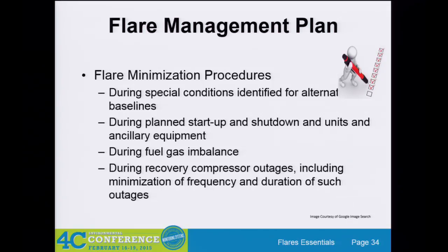But you need to be able to say what you're going to do to try to not flare during those periods. Do you have a means to shut off your purchase gas quickly? You don't want to be buying gas when you're fuel gas long. So how do you make sure that you're not purchasing extra gas? And the same goes for flare gas recovery outages: how do you minimize that gas?